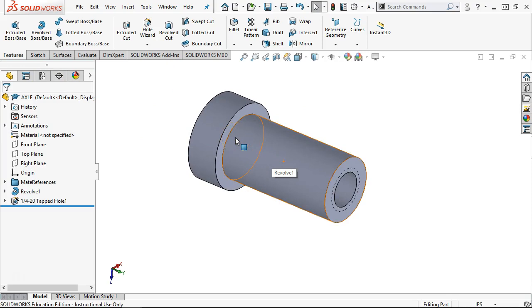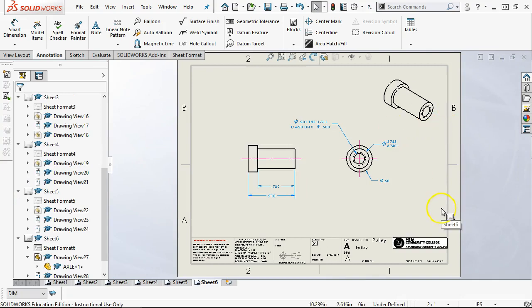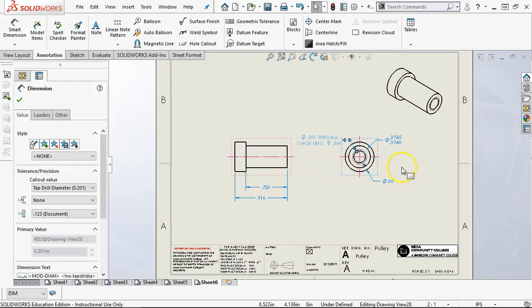The other side of this is also the assembly. Whoever is the lucky person that gets to put all 2 of these together, or all 2 million of them together, is going to have to pick up a screw. With 3/8, that's 1/8 inch of engagement. If we go to 1/2 inch, that would be 1/4 inch of engagement. For a 1/4-20, that's 50 thousandths per turn. Do we do 3.5 turns, or 5 turns? Or we pick up the drill driver and go zip, and it's set to torque and it closes up.